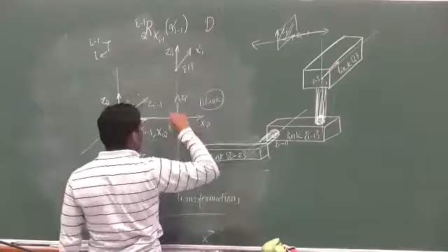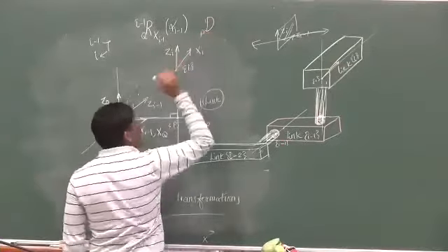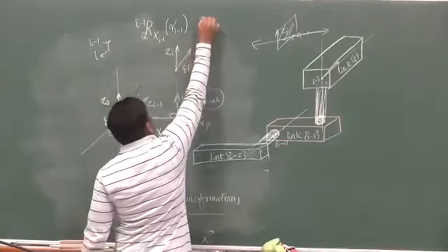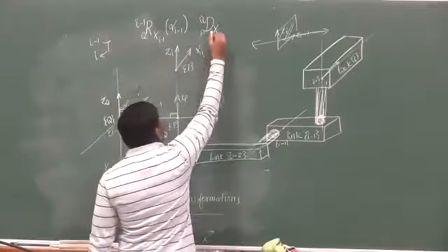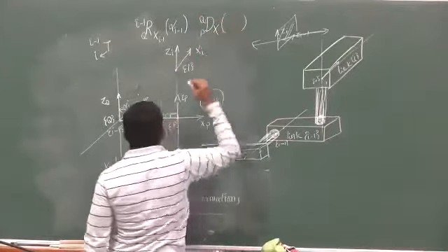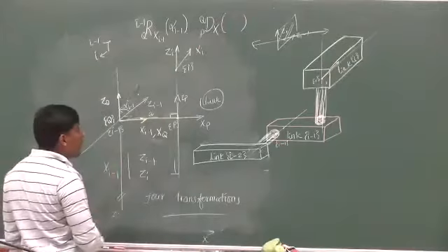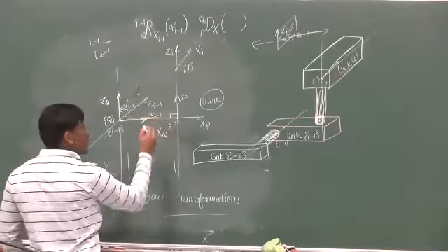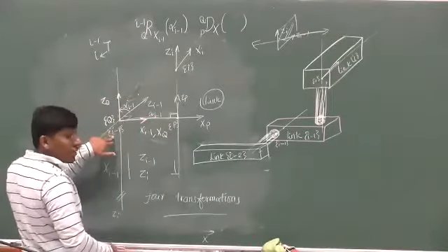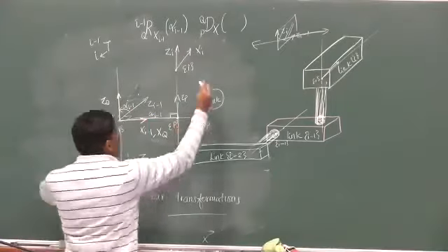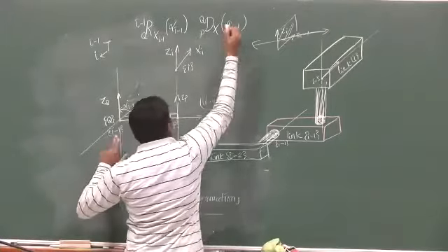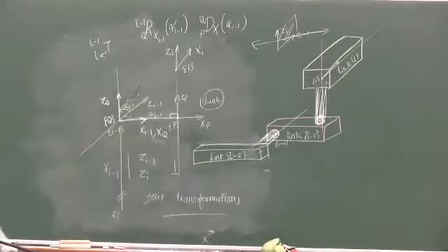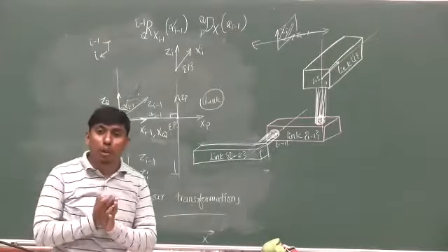You can say what we have obtained. We obtained the P as the frame. So with respect to Q, we have translated along X. The distance we are going to call A. It is what we call link length, and it is with respect to the original frame. This is with respect to I minus 1. That's why we call this A I minus 1. So these two operations we have done with respect to the link.